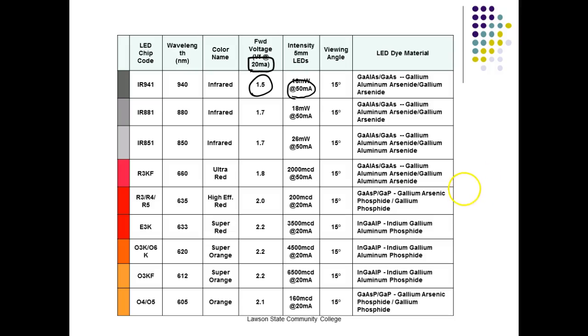You understand. So let's say I've got 120 volts DC over here, and I want to run this LED. Well, first of all, I'm going to put a resistor, right? Well, what size resistor? Well, if this is 120 volts, this guy here is going to drop 1.5 volts. What would I need that resistor to drop? Yeah, 118.5 at what current? At 20 milliamps. R is equal to V over I, 118.5 divided by 20 milliamps. There's my resistor.